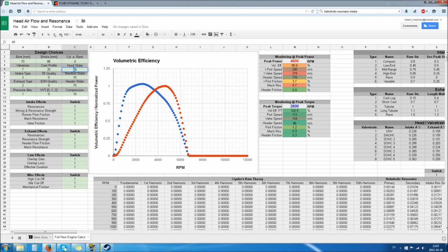And if we want to go a bit more on the cutoff there, yes, you see you can move this a lot by not even touching cam profile, which currently in automation is not possible. Basically everything is done by the cam profile alone and not so much the actual flow limiting or allowing parts of the engine. Okay. That's very good. We have our nice little eco engine, which has very shallow power curve on top and a harsh drop off there. But now let's make a very high revving engine.